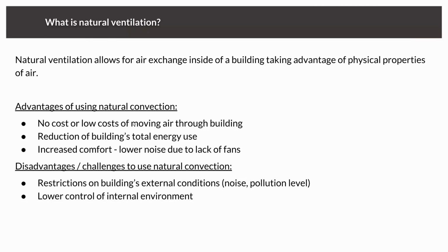Natural ventilation, in contrast to forced ventilation, means that the flow is induced by a temperature gradient inside my fluid flow domain. Just to give you an example, if a gas gets heated, the density drops. When the density drops, I get lift, and the hot air rises up. And that's basically the chimney effect. We can now try to leverage this effect to ventilate a building without using any energy at all. And it has a lot of advantages.